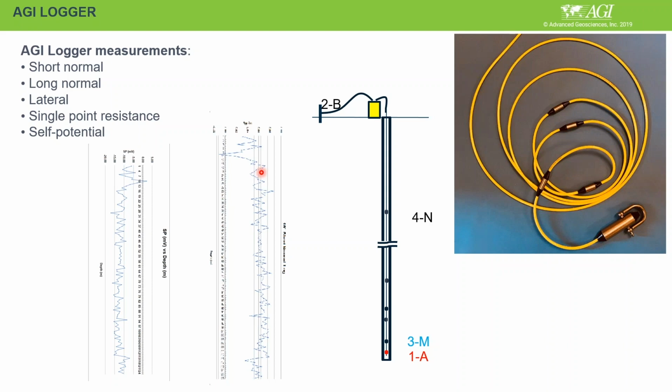That means the saturated zone water can permit the current to go through from the inside of the PVC to the outside. So you can use PVC if the borehole is not stable, then you need to put casing. So if you want to put casing, put slotted PVC, which I mean is PVC that has holes.